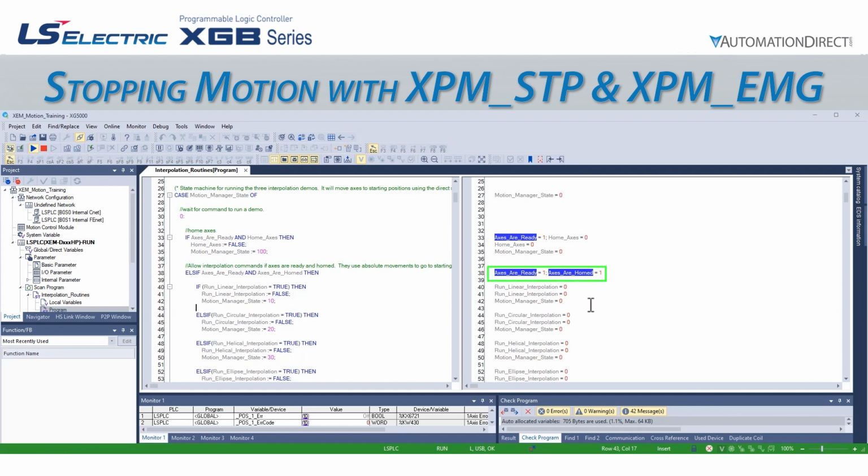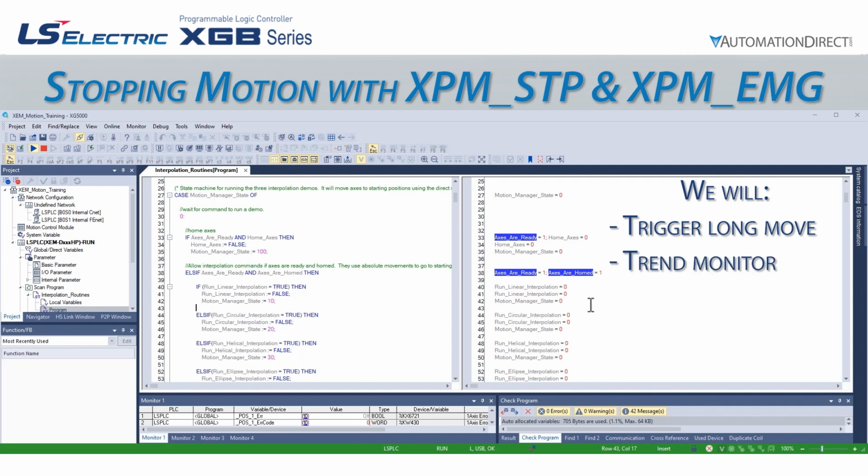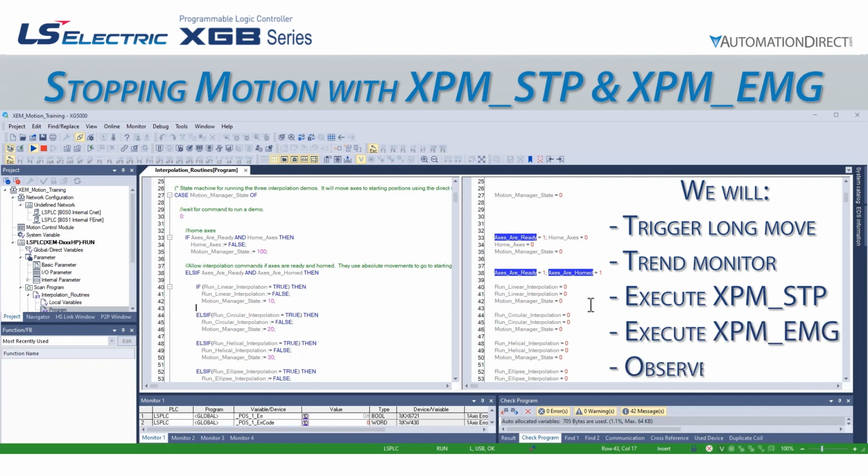We can see the axes are ready and axes are homed bits are both high. We have also already configured our axes in the XGPM software in a different help topic. Please refer to it and the product documentation for more information on axis configuration prior to attempting any motion. Let's trigger a long direct start move, verify that motion is occurring using trend monitoring, and then trigger a decelerating stop and an emergency stop to see the difference in the system behavior for each.